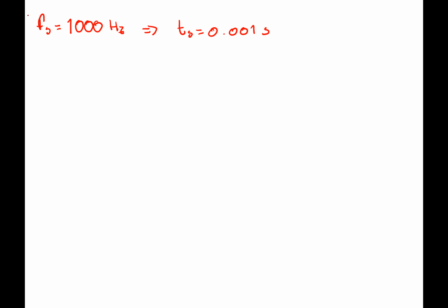So we want to figure out if we can use this sensor to measure velocity at 10 degrees per second. To do that, we need to find out first the resolution of our sensor, which is going to be a full rotation of our sensor, 2 pi, divided by our resolution.